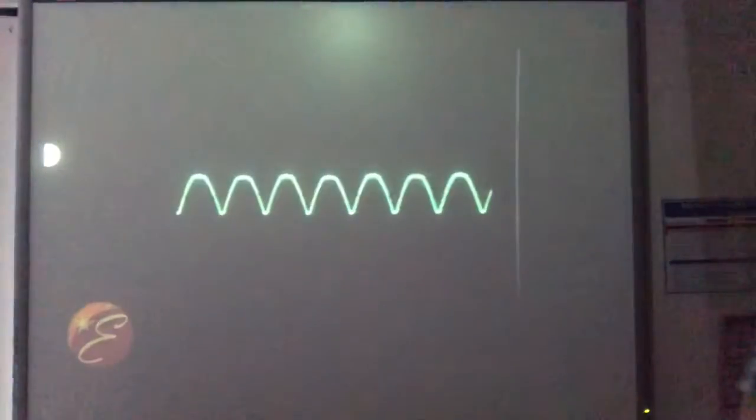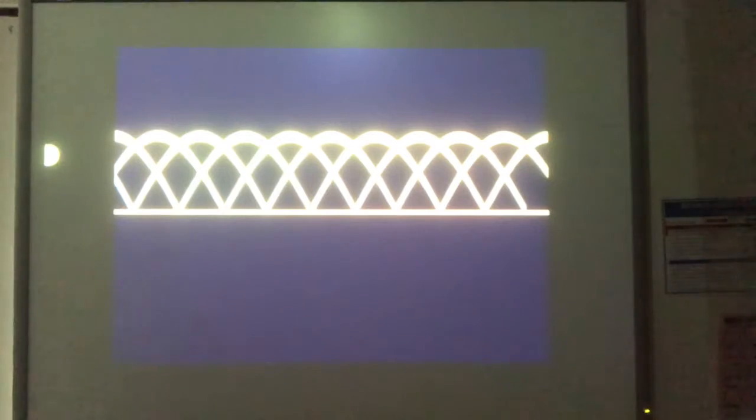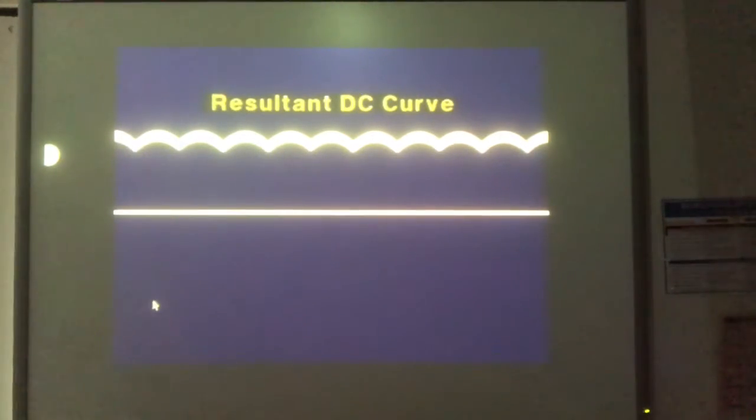The direct current produced by a single coil is pulsating and unsuitable for most applications. Therefore, practical generators have many coils and many commutator segments that can produce a voltage that pulsates very little and is usable.